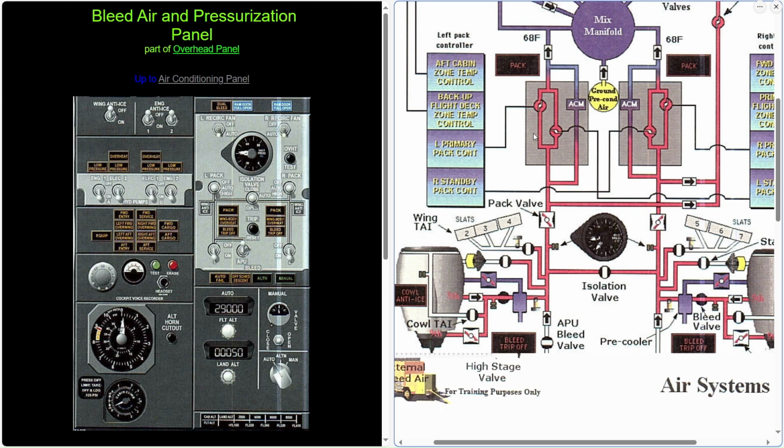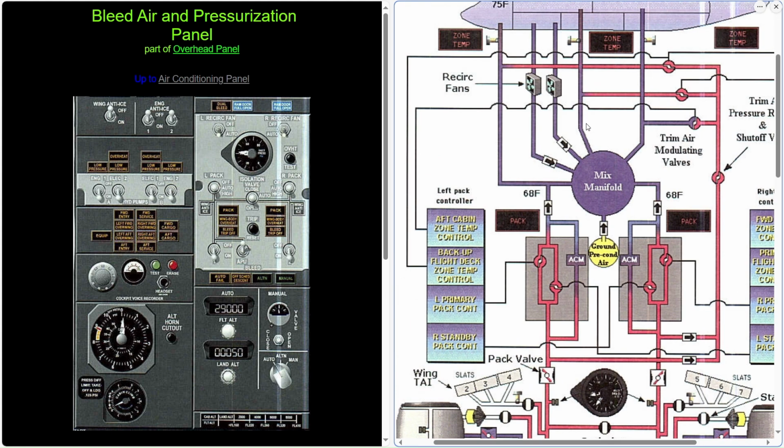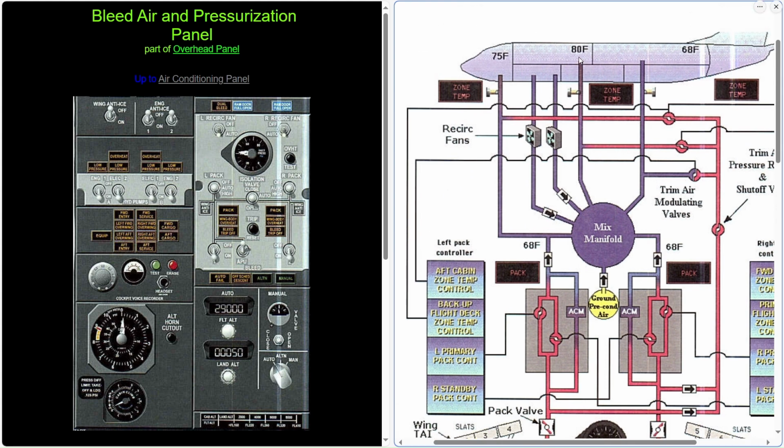There's a lot of energy spent here, so what they can do is just use the air that's already in the airplane, go back into the air mix manifold, and then connect it with the other temperature air here in the mix manifold to get the temperatures that you want. So it may be 80 coming in, it'll be 85 going out, but that air that's being recycled is a lot easier to get down 5 degrees than, say, the other air that's coming in through here.